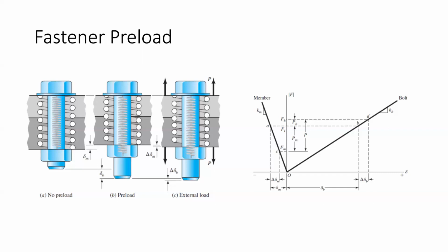And the interesting thing is that it's dependent on the bolt torque. So as we tighten this bolt, obviously the system compresses, but how do you relate this torque on this surface to the amount of axial force that you have in the system? So that's also somewhat complicated, but the mechanism here is as you tighten this bolt, you have two torques that originate. You have the torque from the friction between the thread and the mating material, and that friction causes a torque that resists you turning the bolt more. But you also have the friction between the underside of the bolt head and the material. So that's kind of like a circular friction between the surface of the bolt and the material, and that also reacts your torque strength. So again, you can correlate that torque to the amount of preload.